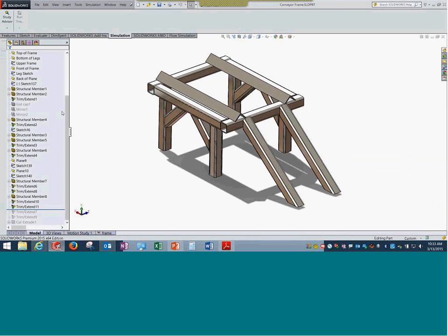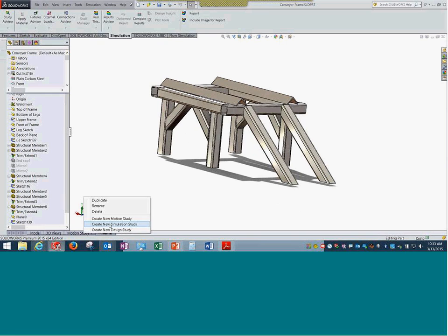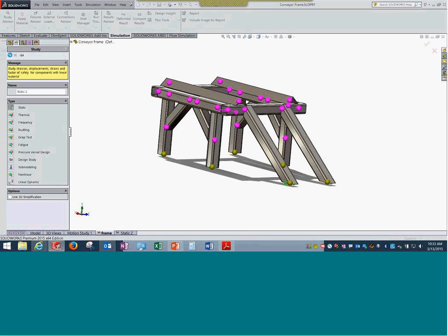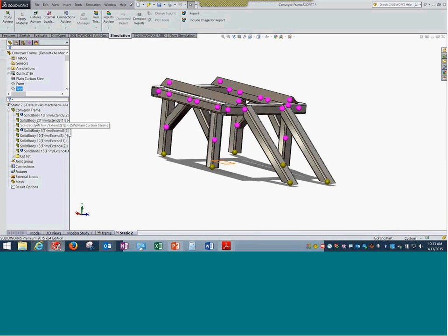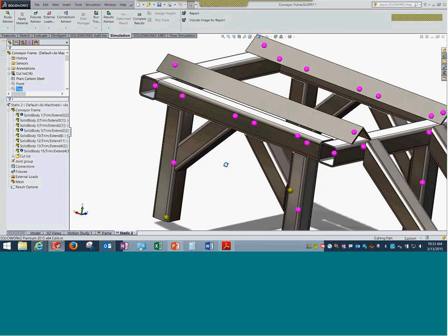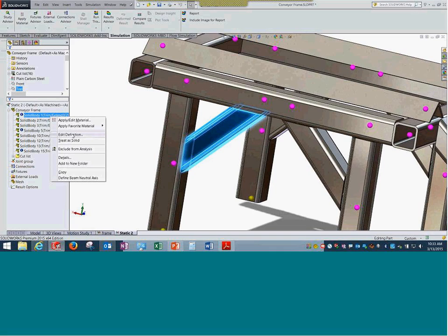Okay. Let me go back. If you see this entire setup, it is made up of weldments. At least over here, that should clarify. So typically when I create a new study of this, automatically these weldments will be treated as beam elements. We don't worry about it. It could be small entities, but they are treated as beam elements. But beam theory says that the beams need to be of at least a certain amount of length. They can't be smaller than that.